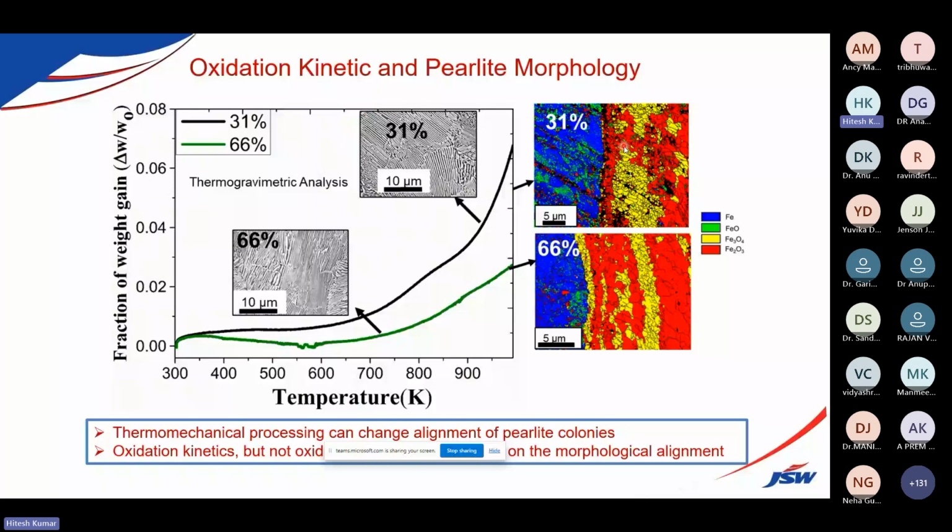In backscattered mode, we tilted the sample at 70 degrees, and the backscatter detector captures all the electrons scattering from your sample. Normally the angle is 65 to 75, but 70 is the optimized one.